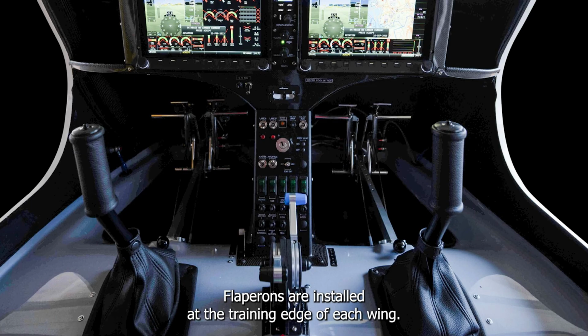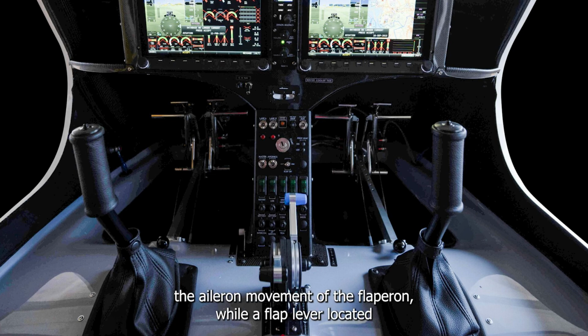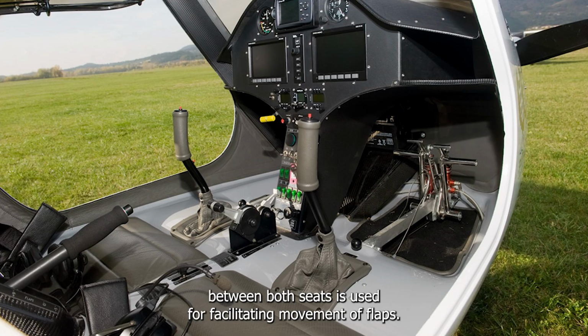Flap ailerons are installed at the trailing edge of each wing. Two different control levers are used for flaps and ailerons. Lateral movement of the dual flight control stick affects the aileron movement of the flap aileron, while a flap lever located between both seats is used for facilitating movement of flaps.